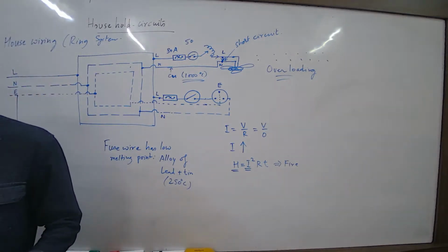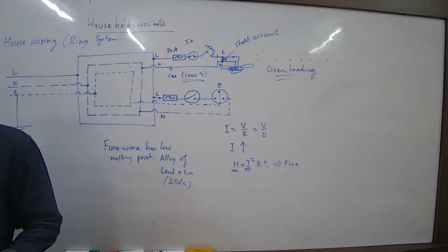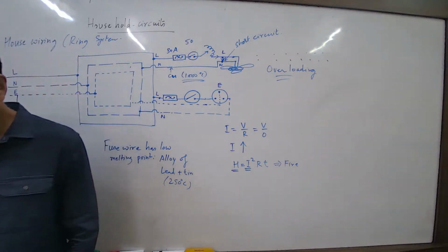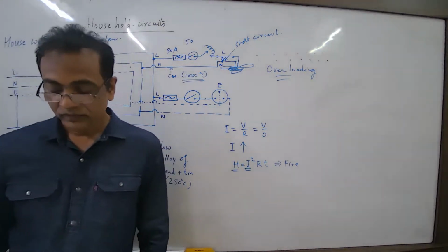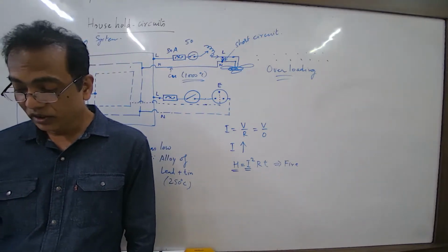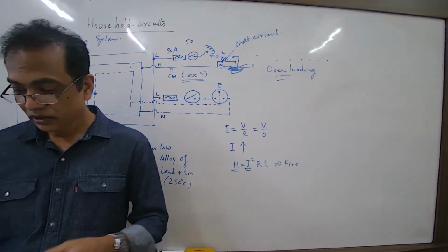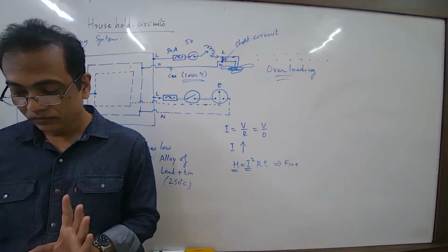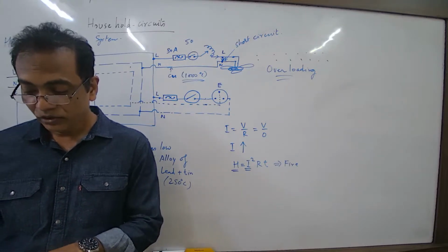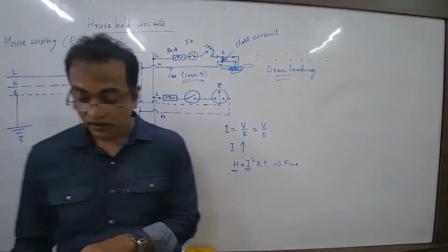Come on, the first one, what is it, figure 9.5? How will you connect a bulb and a socket in a room to the mains? Draw a labeled diagram in support of your answer. So how have you done it? For the bulb, do you require earthing? No, because you don't touch the bulb, right? So just a live and neutral will do. So the connection shown to the bulb is only to live and neutral, and you have a fuse and a switch to operate the bulb, right?